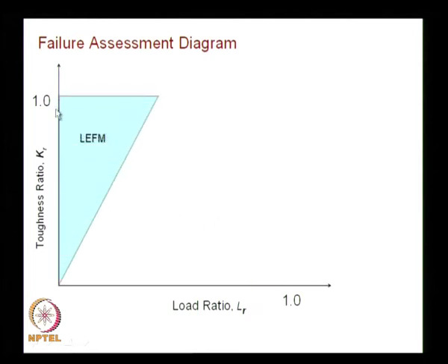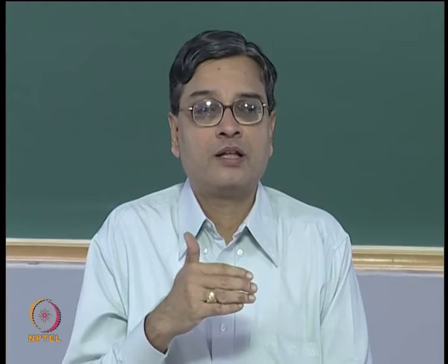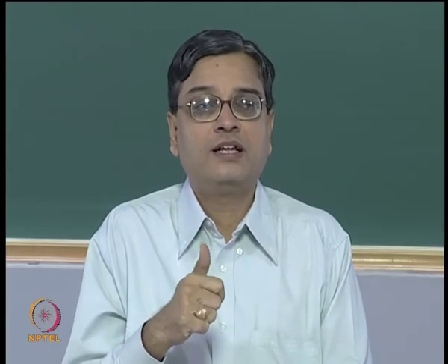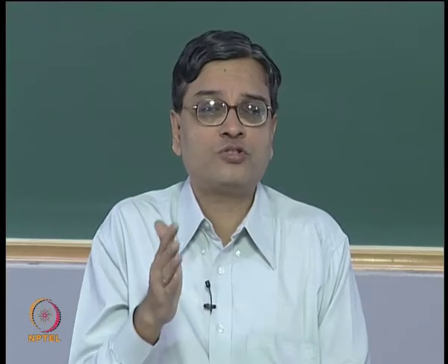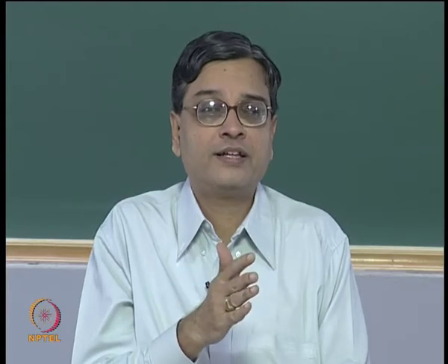People had looked at very small load ratios, where essentially it is in the domain of linear elastic fracture mechanics. I think you need to make a sketch of this; it is a different figure than what we had seen earlier, and this gives you an appreciation of how people have approached fracture mechanics, and we always borrow some of these ideas from what we know in conventional design analysis. We have seen in conventional design analysis you have sigma ys, the yield strength from a tension test, used for failure under combined loading. In mixed mode fracture, we have found the K1C value was used.